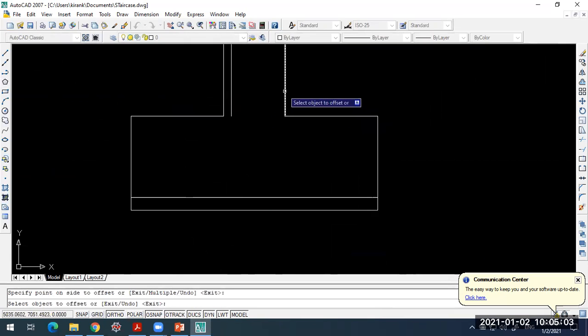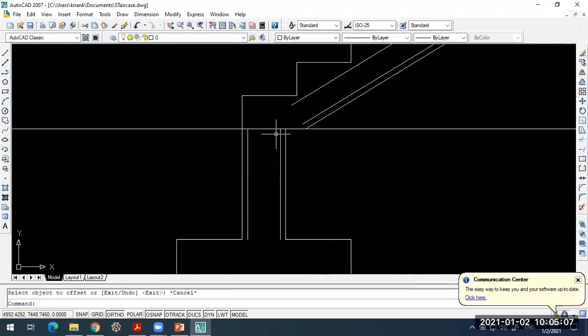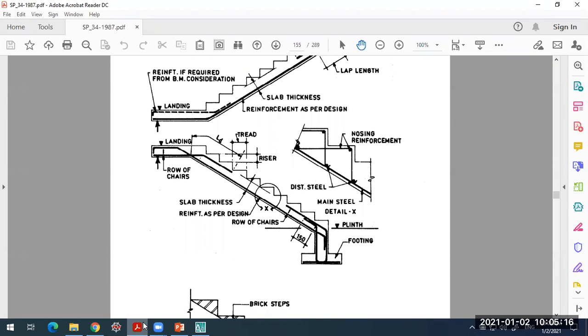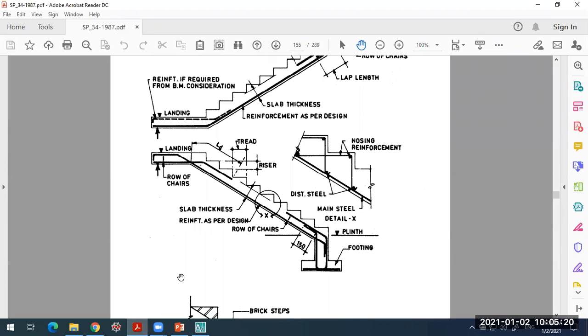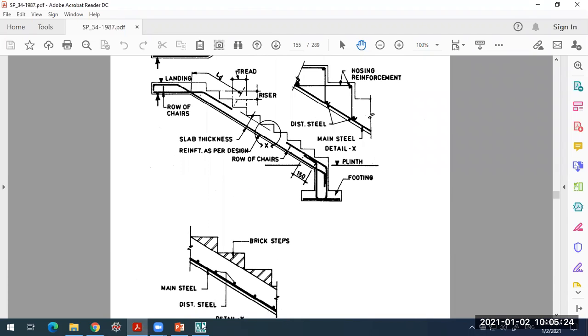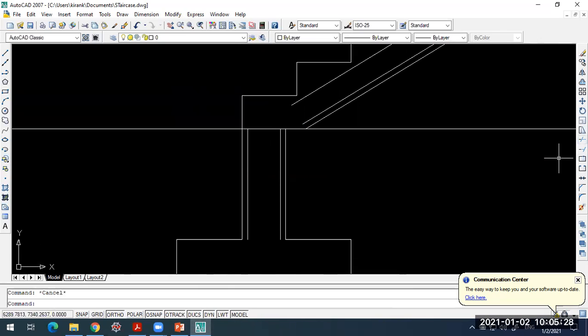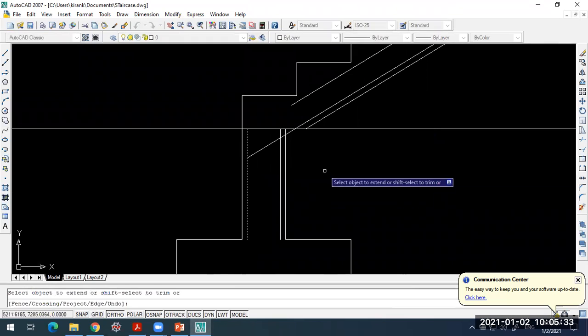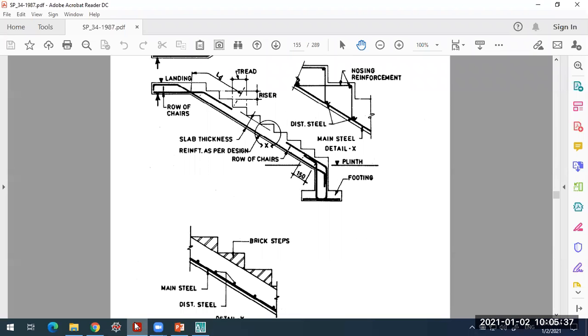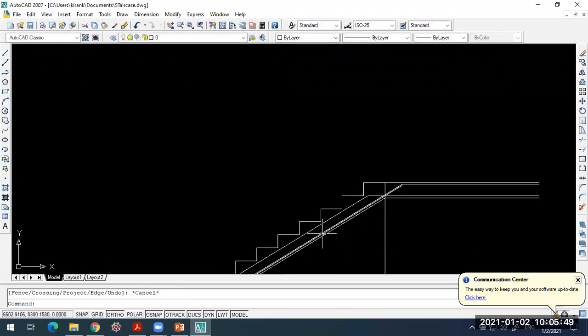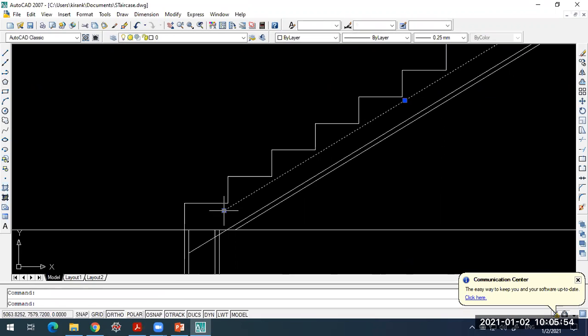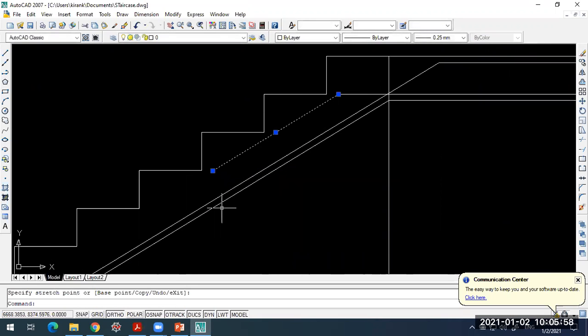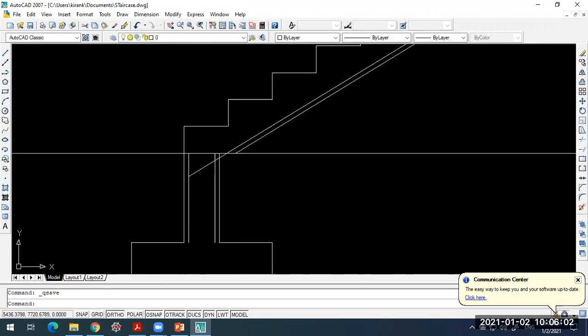We don't have any particular details of the reinforcement in the foundation. These are just to show how the foundation will merge with the staircase. The top parts here. So the landing slab bar will continue. Okay, and this top bar is to take up any negative moment in case it arises. That is the additional bar being provided here. This we shall stop here only after the development length. Yes, this will stop at this point. Okay.